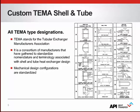The P-type is a floating rear tube sheet suitable for thermal expansion, contraction, and bundle removal. It utilizes packing on the shell side, compatible with low-pressure, non-aggressive fluids such as water or glycol, with the more aggressive, higher-pressure fluids such as a hot gas or a high-pressure liquid on the tube side. The S and T are the least cost-effective designs, but they allow for higher pressure on either side with the benefit of a removable bundle as well.